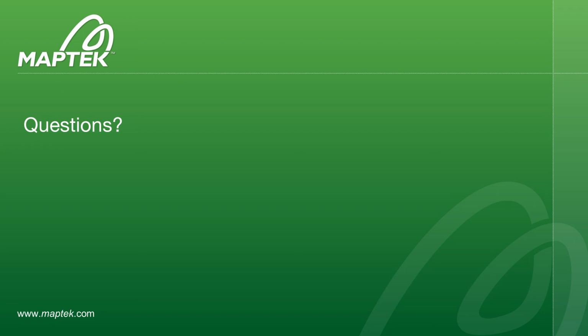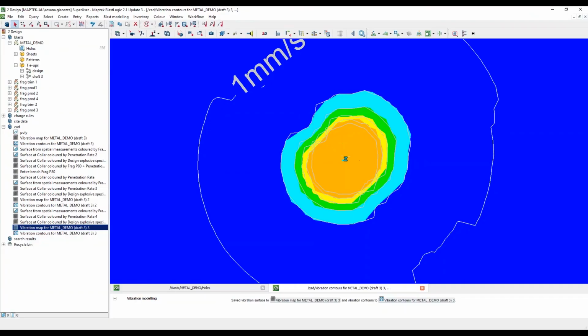The other thing you mentioned at the end about using the vibration model for presentations and graphs and exporting it. How easy is it to export images? Well, if you don't want to take a screenshot, the best way to get a high quality image is to use the little camera tool in the top toolbar, that will give you a high resolution image of the view that you currently have on the screen, which is great for presentations. Great.